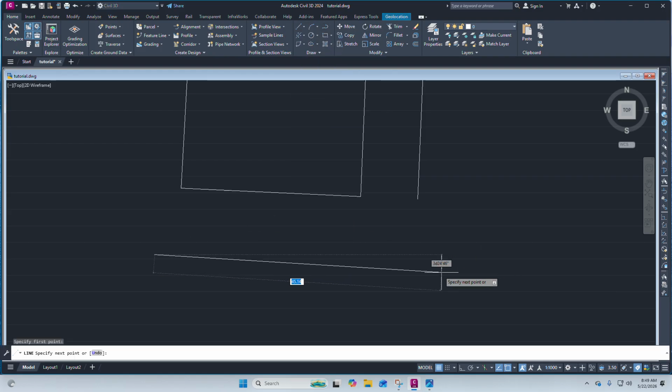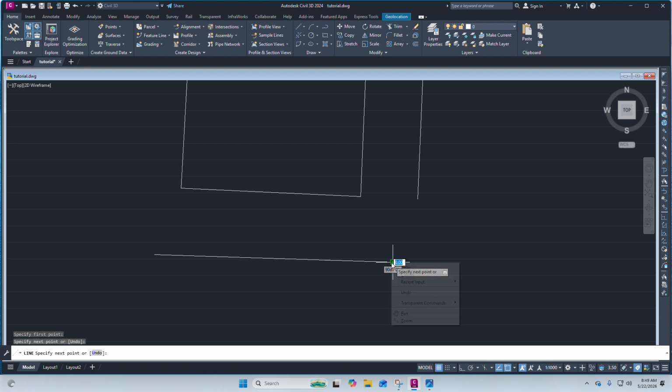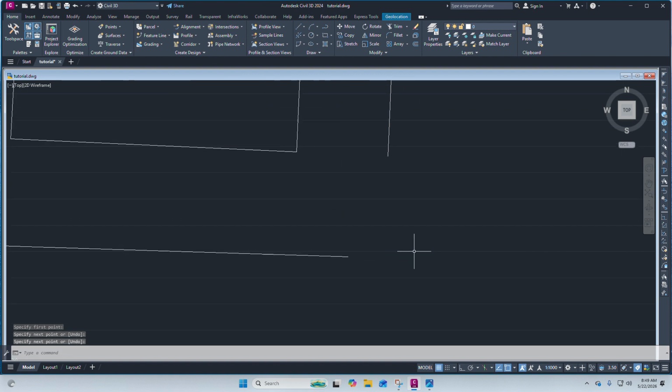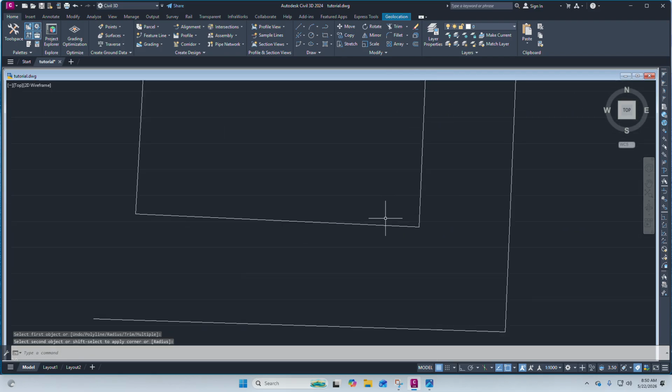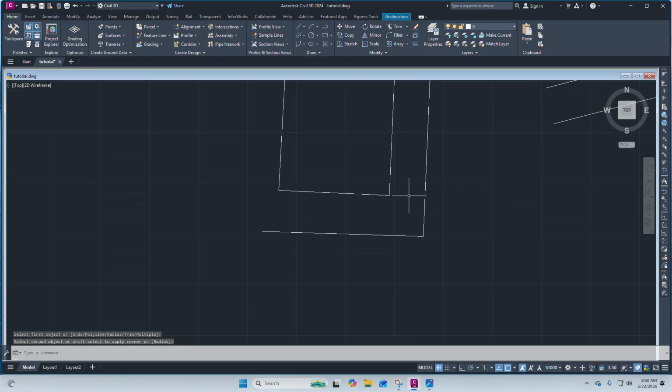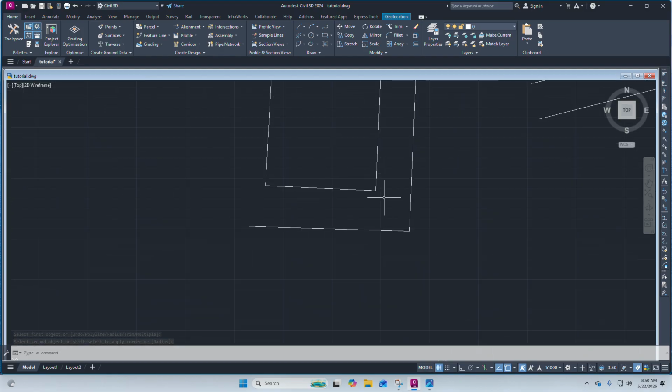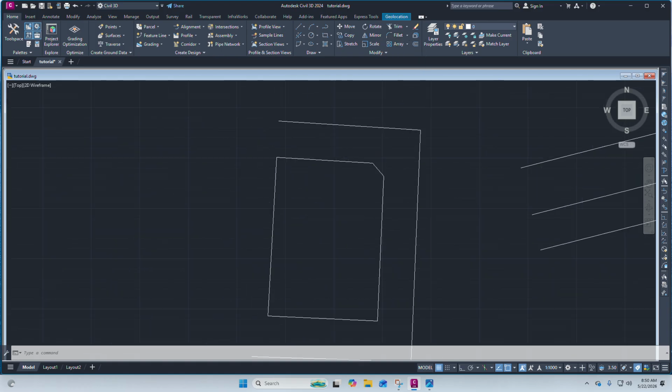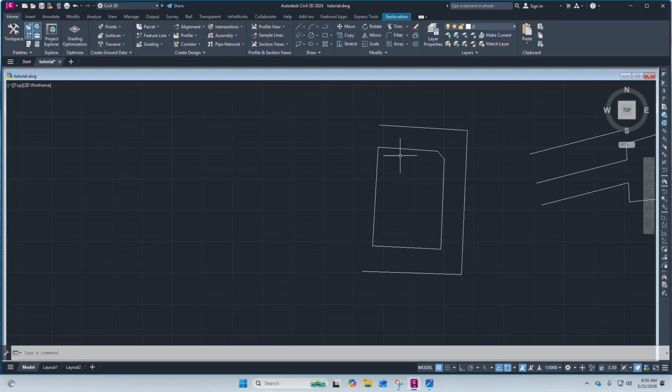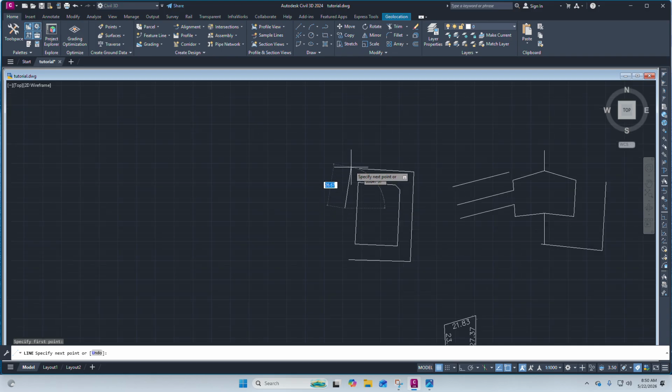Suppose you have another rod at this point. Let us first of all use the fillet tool to join this line and this one. Fillet, select that one and that one. So now you need to have shortcuts, and you have a tool to do the chamfer. You don't need to do it manually like the way we have done at this point. Let's do it manually for the last time.